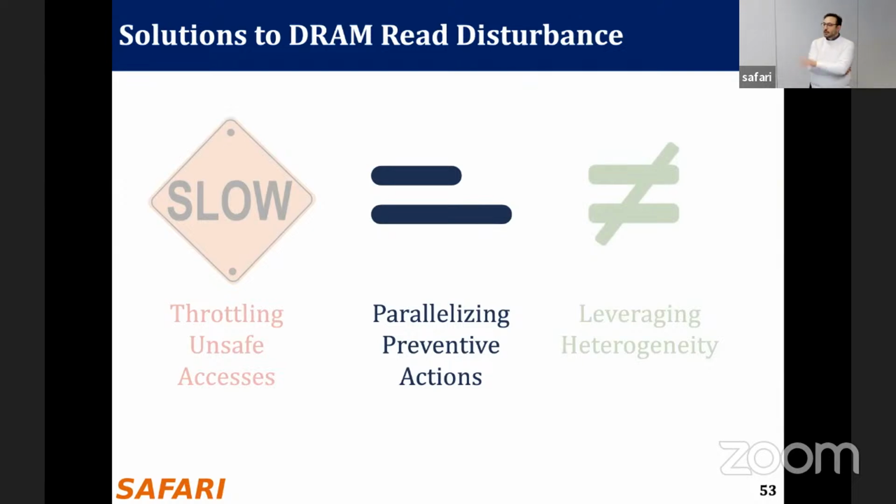On a high level, it definitely makes sense. In BlockHammer's constraints, since one of our goals is to ensure compatibility with commodity DRAM chips for this memory controller-based mechanism, we have to assume that we do not know the physical layout of the DRAM row, so we cannot identify precisely which row is next to which row. So we do not know which row to refresh. That's why we cannot combine them in this space of constraints, in this universe.